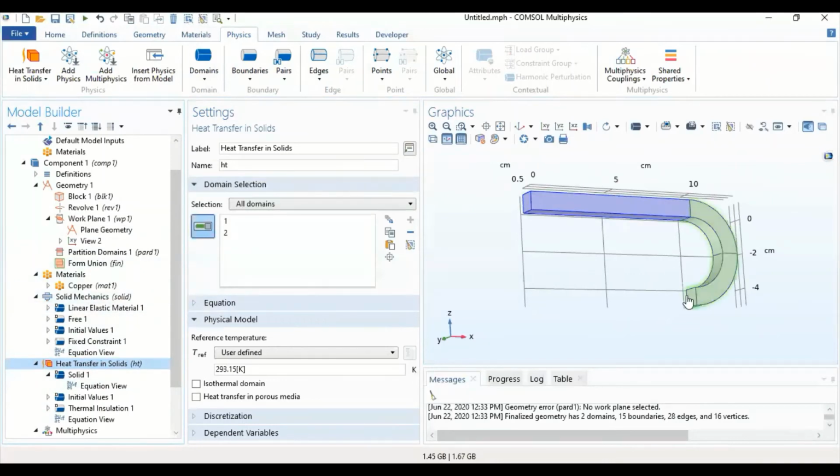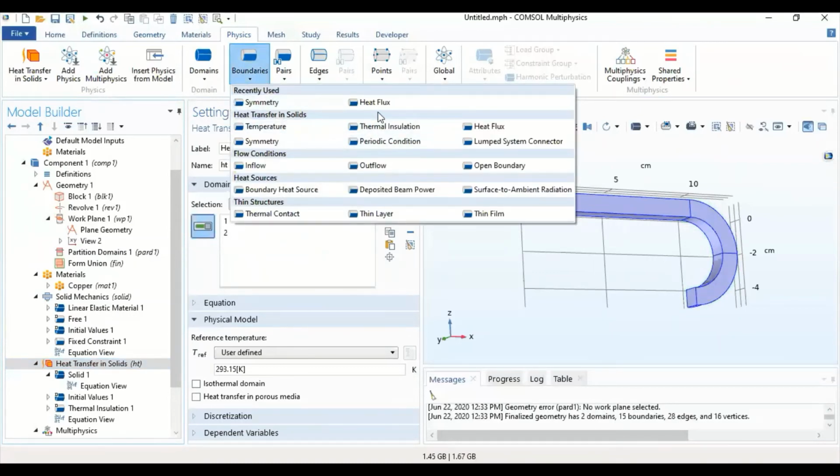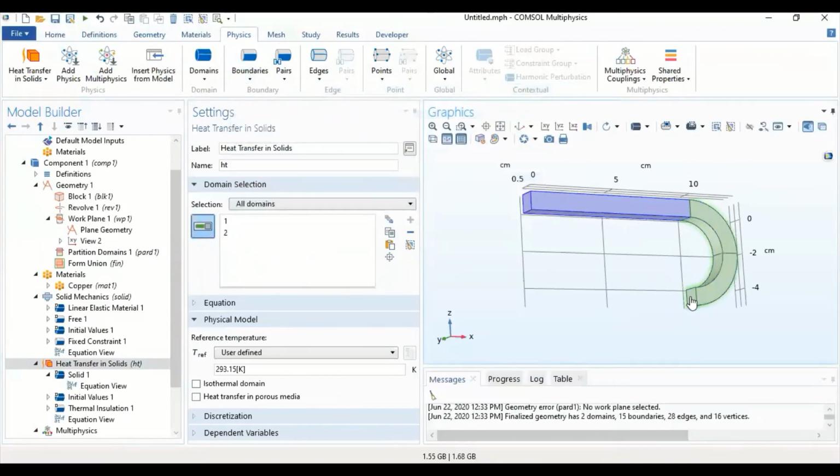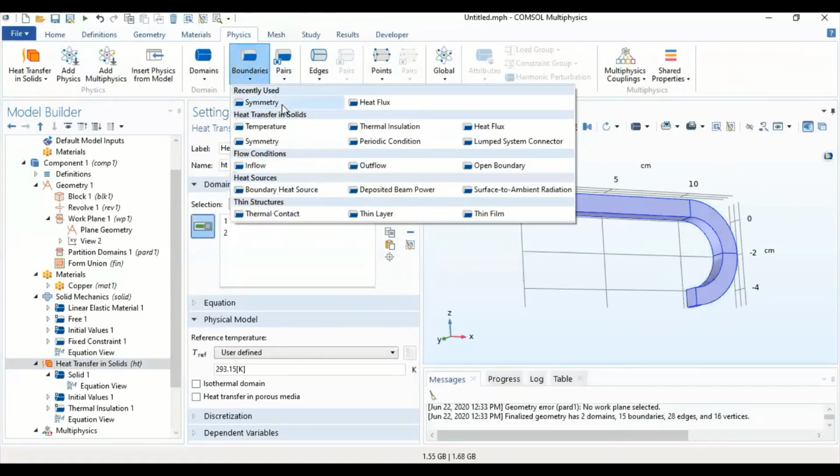I can also fix it from the other side here to a wall, and if it expands, it's going to go in the ZX direction, more or less to the right-hand side. And I can also use another boundary condition, which is, for example, a roller. A roller allows movement in a single plane, but not the other. If I use a roller condition on this face, it can move in the Z and X directions, but not in the Y direction.